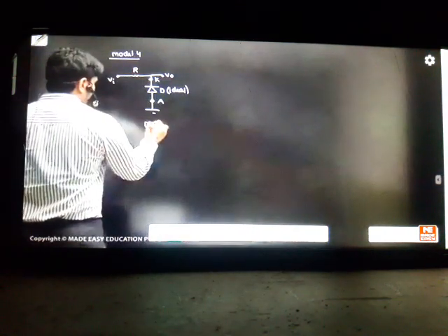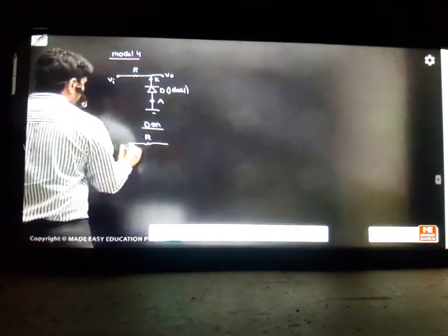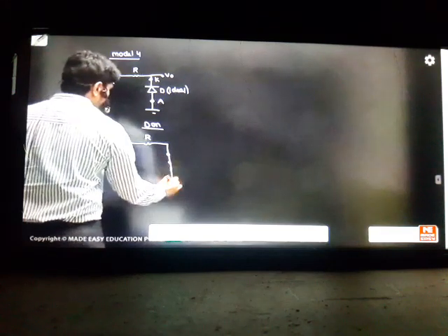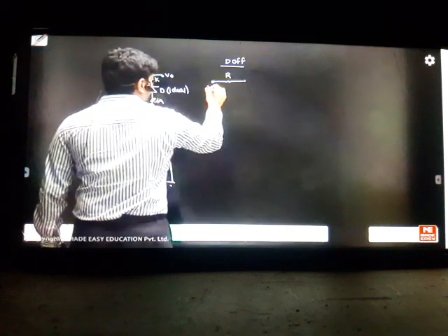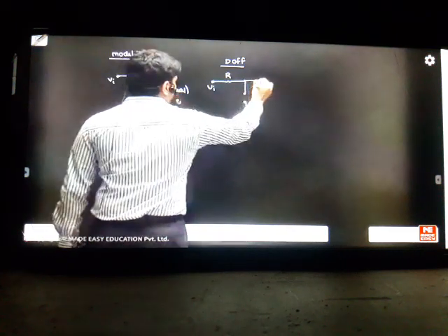I'm designing the circuits. So this circuit also has two possibilities, correct? Diode on is one case, where we have resistor R and this is VI. Making it on means a short circuit to the ground. This is your output. Output became 0 in the first case. And if the diode is off, with resistor R and this VI, the diode is an open circuit. Output is equal to input we got.